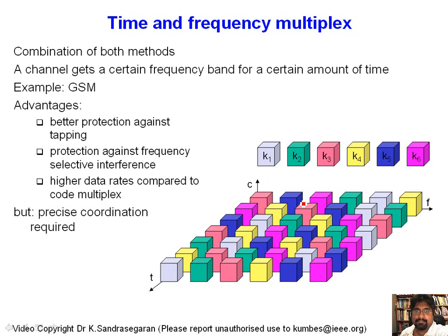Okay, but again, it requires very precise coordination, because now we have to know the frequency hopping pattern that is used at both the transmitter and the receiver. You not only have to synchronize in time, but you also have to synchronize in frequency between the transmitter and the receiver.